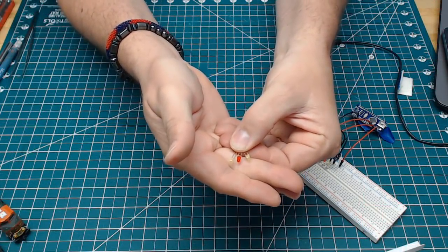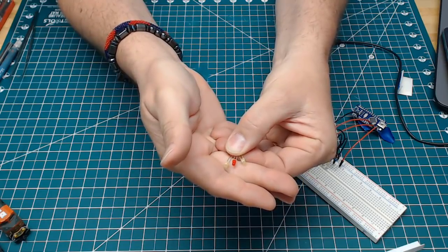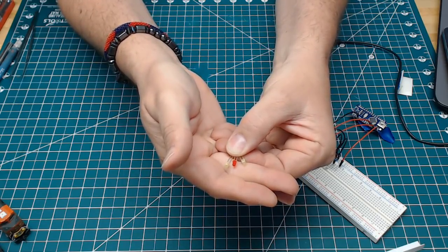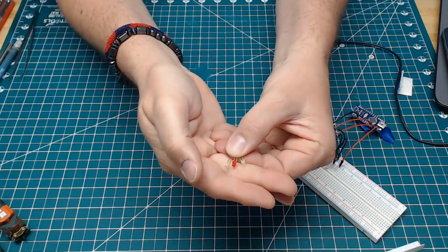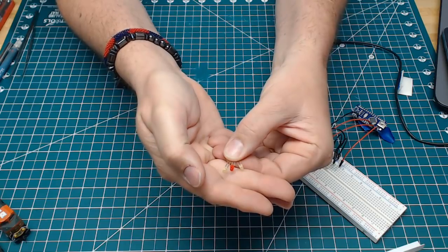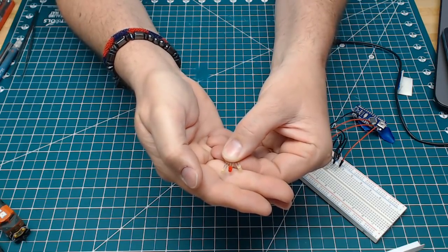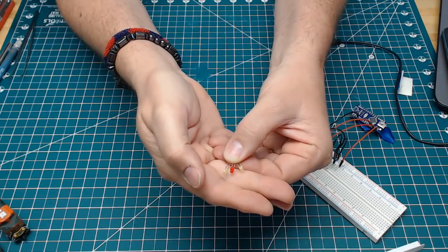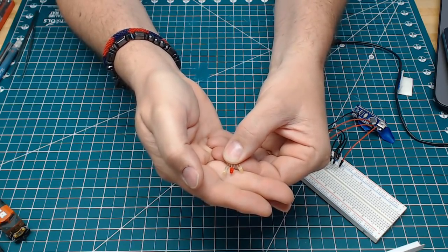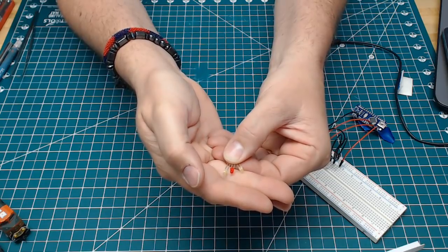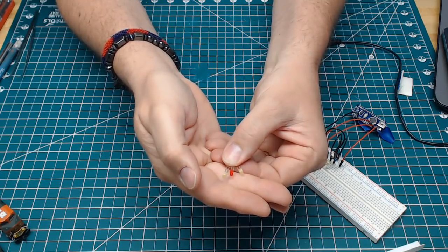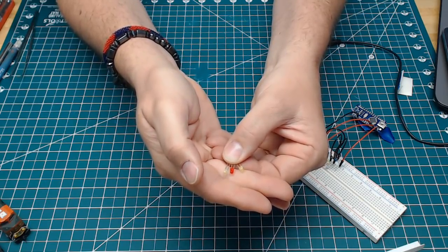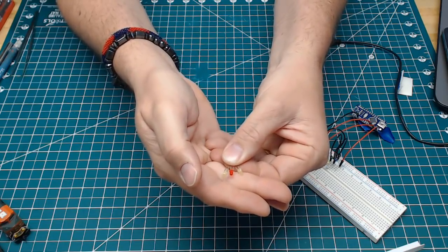So I want you to see the LEDs that I am working with. I am using 3mm LEDs, which are a fairly small LED, and it makes about the right amount of light, I think, for my in-scale application. You can use any size LED for this project. The important thing is to make sure you have the specs on those particular LEDs. In other words, you need to know what voltage and amperage those LEDs run at, what their maximums are, because that will be crucial to choosing the right resistors, and you have to use resistors with any LEDs to keep from burning them out when you hook them up to the Arduino.